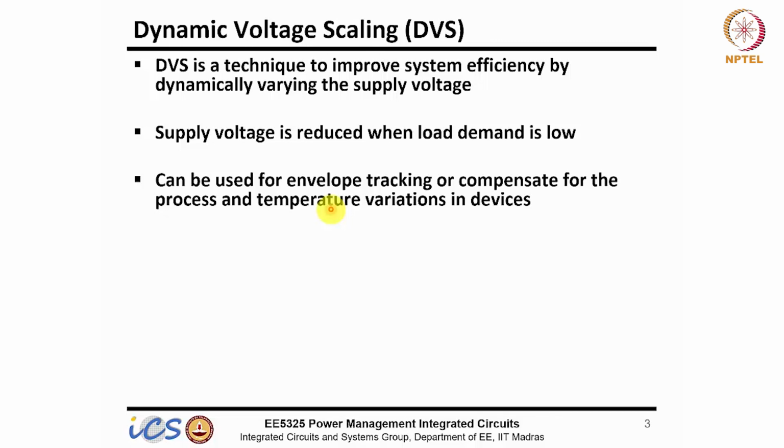So what you do in dynamic voltage scaling is you design at a typical corner, and I think we talked about how you track the PVT, you can have a ring oscillator. So let's say you are able to track the process and temperature, that will give you the code.